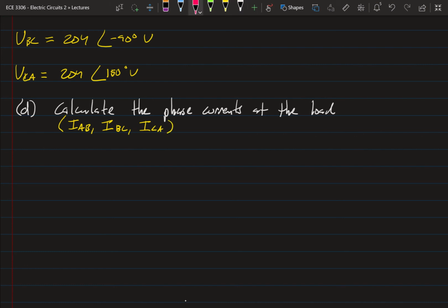So the equation for IAB is actually equal to this. It's a little bit different. It's 1 over the square root of 3 at an angle of 30 degrees times just IaA. And I've figured out 1 over square root of 3 at an angle of 30 degrees. Again, I played it kind of fast and loose with the rounding, but I got 0.5 plus j0.3.